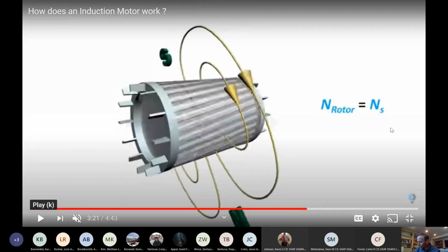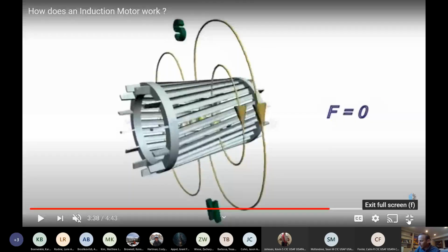So your takeaway for this class is that an asynchronous motor is a way to get rotary motion that's very simple. You saw that there's very few moving parts. You just have that rotor, and the rotor would be supported by some bearings. But there aren't the more complicated, intricate parts that you get in a DC permanent magnet motor.